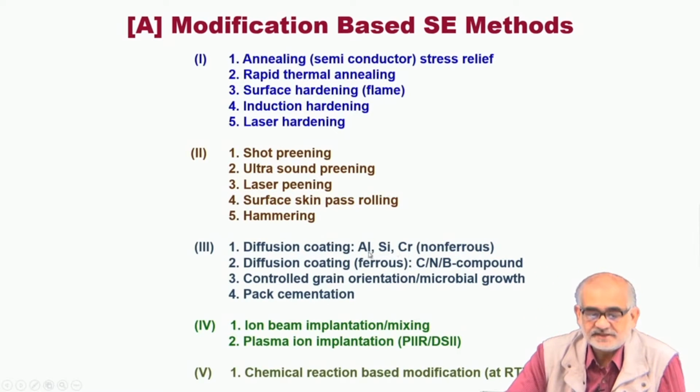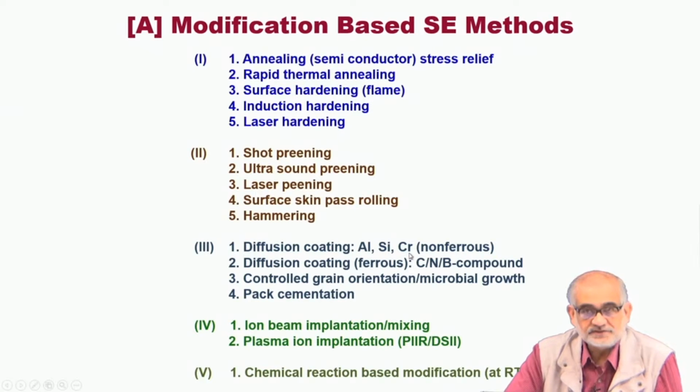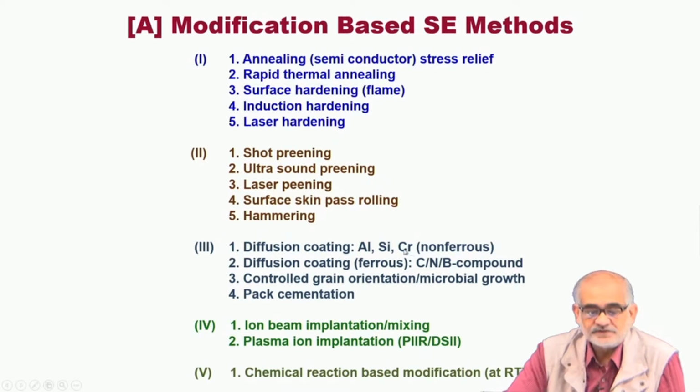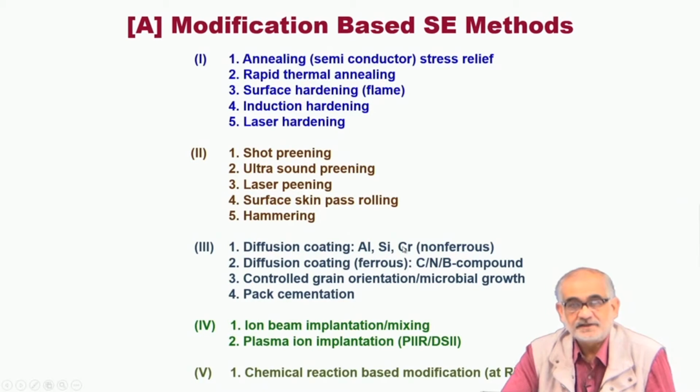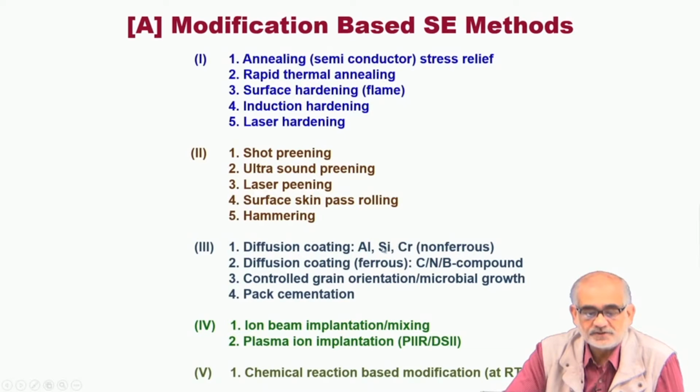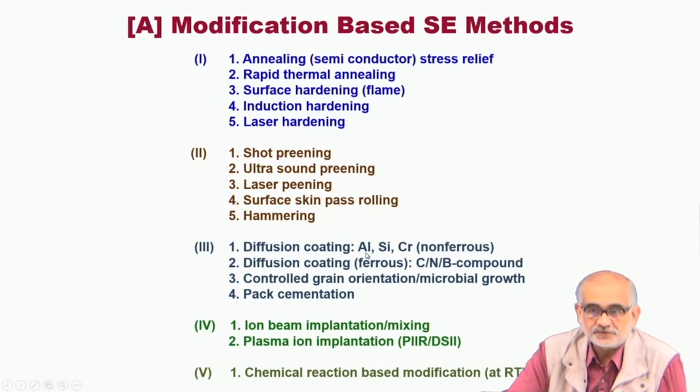The advantage is that these elements create a solute-rich layer onto the surface, which when exposed to high temperature preferentially creates oxides of these elements, which are not only very stable and having very high melting temperature, but also quite adherent to the substrate. As a result, you create a thermal protection system onto the underlying substrate.